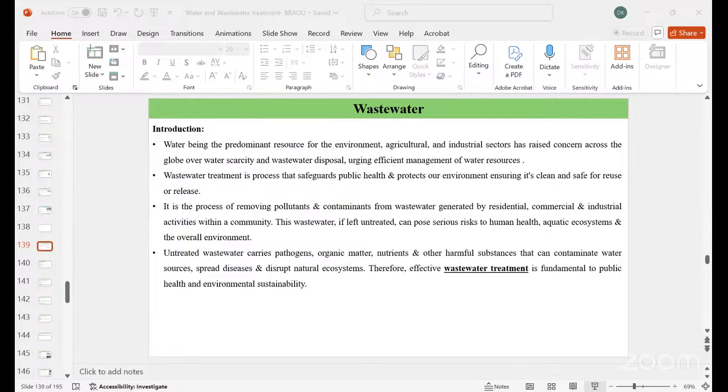The main fundamental concept is BOD, which is a crucial parameter in wastewater treatment. It represents the amount of dissolved oxygen consumed by the microorganisms during the aerobic oxidation of biodegradable organic matter in a water sample over a period of time, usually 5 days at 20 degrees Celsius. The main goal of this biological treatment is to significantly reduce the BOD of the wastewater.